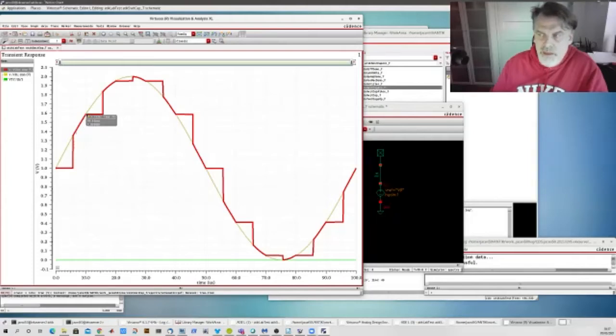And then I will start releasing the switch, sample that voltage and hold it, etc. So I do have some sort of staircase operation going on, and it's probably also important to realize that we track the input during half the clock cycle and hold during the other half cycle. So the operation is a little bit dodgy. It's a little bit of discrete time and then continuous time to some extent.